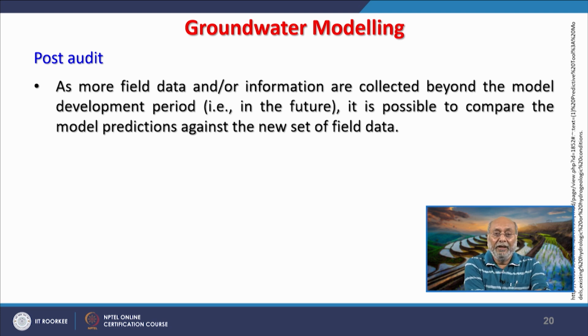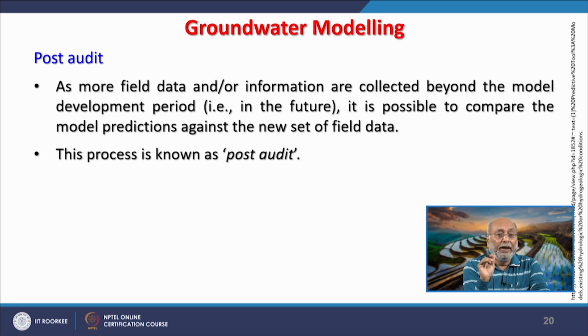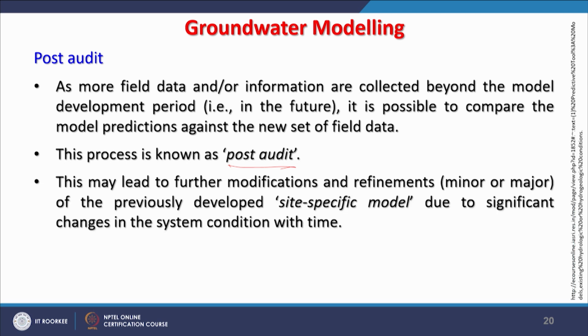That means you are bringing a new set of data which have not been used in the model at all, neither in calibration or verification or any other stage. Now, a new set of data is coming and we are trying to compare that data with the model outputs, and will see how the model has performed. This kind of process in groundwater modeling is called post audit.